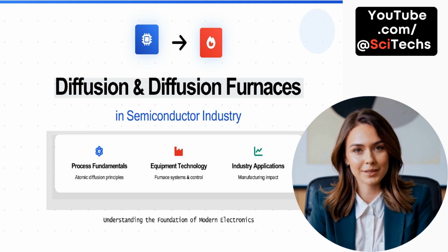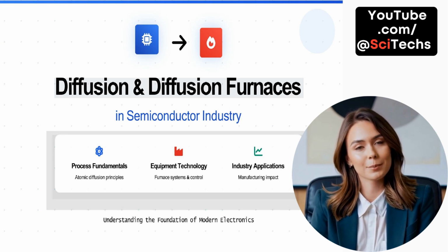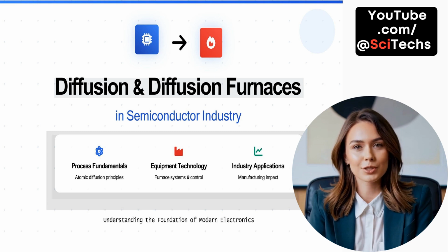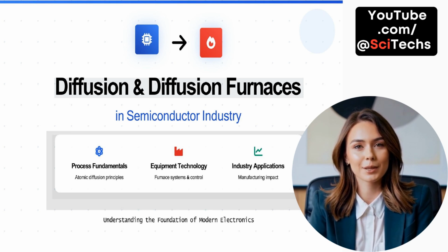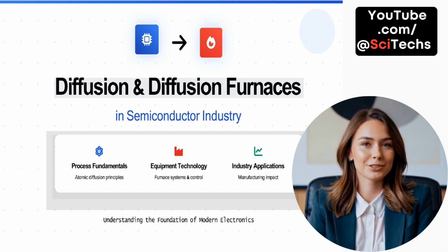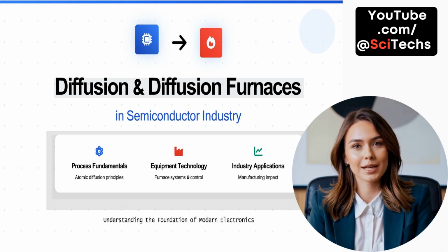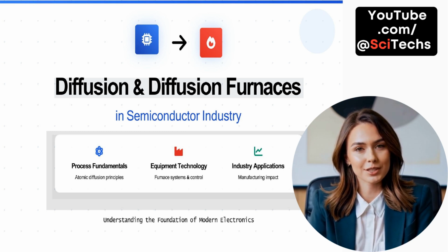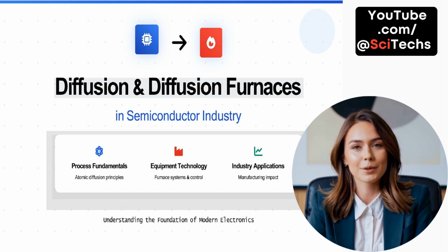We'll explore the equipment technology behind diffusion, specifically the design and operation of high-temperature furnaces that enable controlled and uniform diffusion. These furnace systems include components for gas delivery, temperature control, and automation. Finally, we'll connect these concepts to industry applications. Diffusion impacts device performance, yield, and scaling, making it indispensable for modern electronics. Through this journey, we aim to understand the foundation of how electronics are built from the atomic level up.